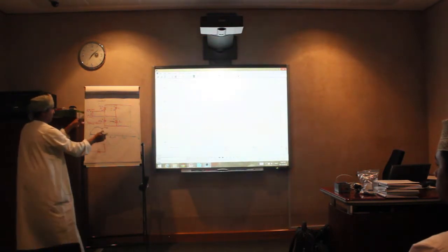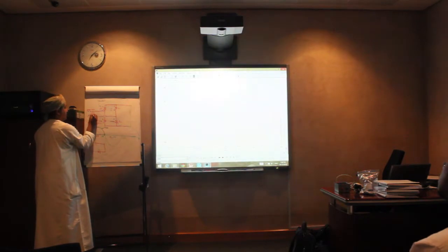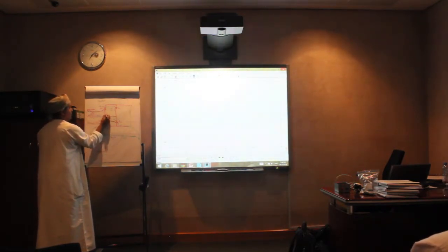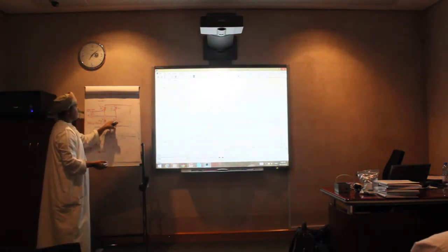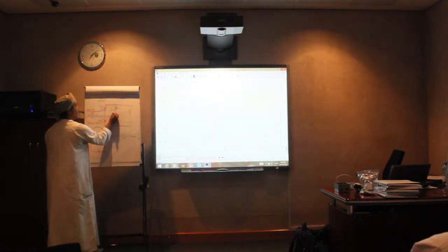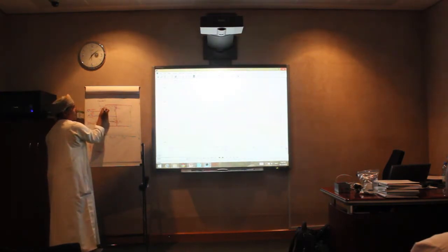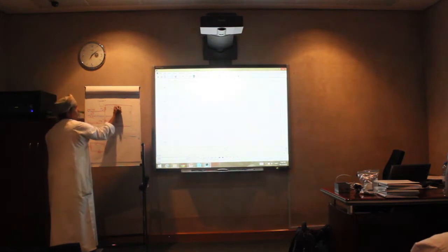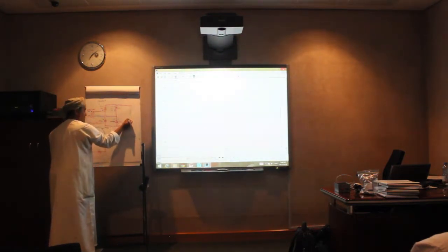Again, if I dot the circuit, if I'm trying to trace, that means the current will start from here, it will go through that wire. When it reaches this point, remember the current will not go to the opposite, so it will go up toward this diode, and then when it reaches the next point, it will not go to this direction because it is blocked by this diode, so it will continue toward the resistance like this.